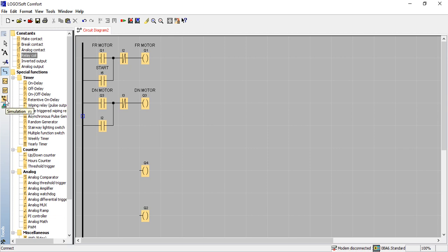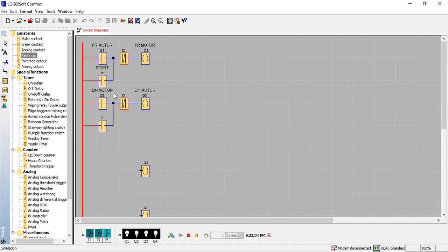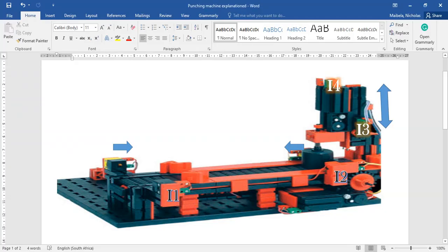So now, we need to face facts before anything else. When I press I5, the current state at I2 is connected, but it's not pressed. Get that right. Now I'm pressing I2. I'm stopping at I2. Where is our item currently? It's at I2. It has stopped there, so that Q3 can be activated.